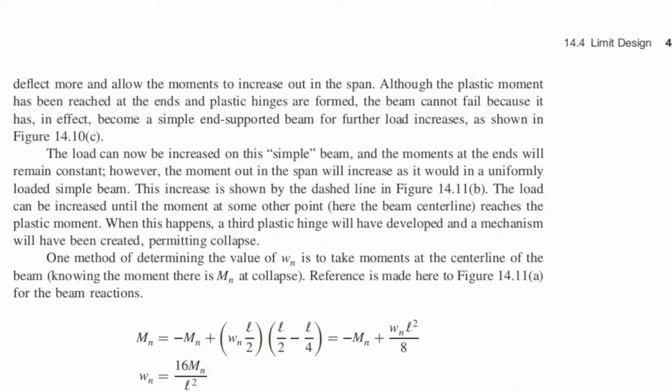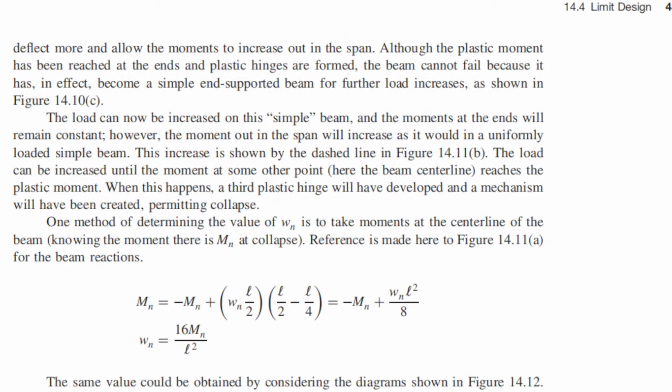So deflect more and allow moments to increase out in the span. Although the plastic moment has been reached at the ends and plastic hinges are formed, the beam cannot fail because it has in effect become a simple end support beam for further load increase, as shown. So actually it can still carry additional load as a simple beam.